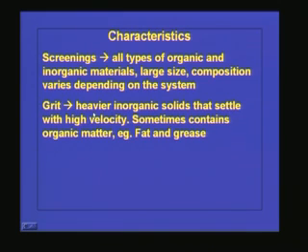It is heavier inorganic solids that settle with high velocity, because the basic design itself is meant for removing heavy inorganic materials from the wastewater. Because if it goes to the further treatment or secondary treatment units, what will happen? It will adversely affect the pumping system and all, because it will create a lot of wear and tear, and unnecessarily we will be getting sludge which is not active. So to prevent that, we provide the grit chamber.